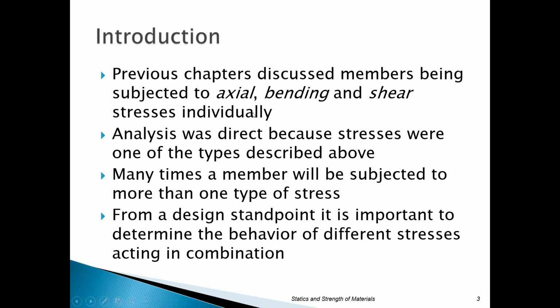So in other words, we have these three things going on, and we looked at them separately, as if you're only dealing with axial, bending, or shear. But what we're going to find out is that a lot of times a member is going to be subjected to more than one type of stress at a time. So from a standpoint of dealing with that, you're going to be looking at combining those things. Because the member is actually experiencing those together, you can't just look at them separately. What you're going to do is combine them and look at the combination. So this is what we call a combined stress.